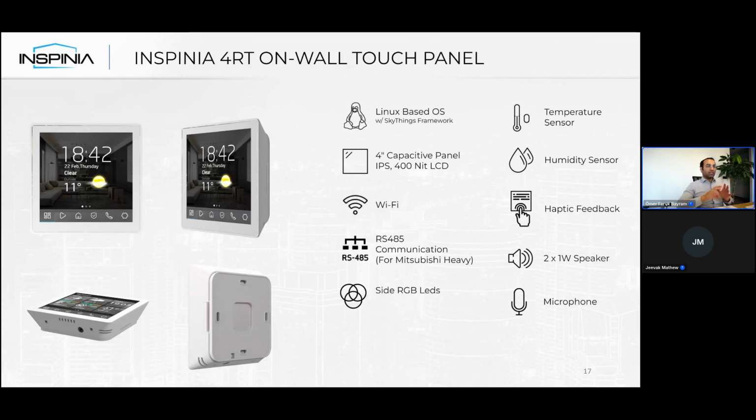When you put this device in, you power it, and then when you connect it to the common network, to the smart home, home or office, over Wi-Fi, you will be able to control Wi-Fi protocols, I mean IP protocols. Enhanced MQTT, KNX IP, Modbus TCP, for example, SES IP. All these protocols can be combined or used separately. It doesn't matter. When we connect to the network, we can control many things over IP as well.